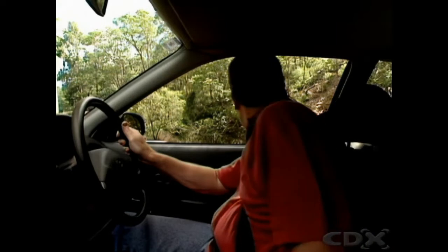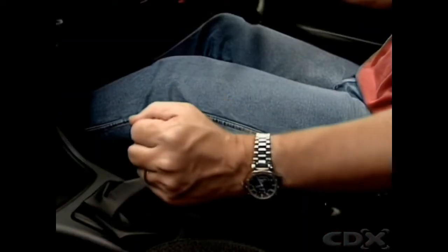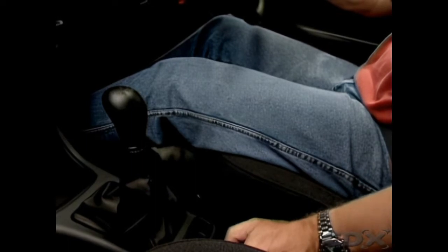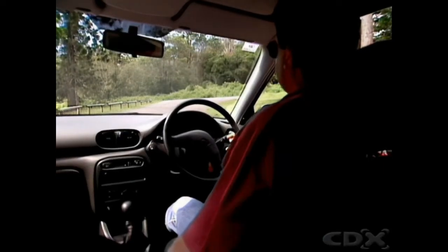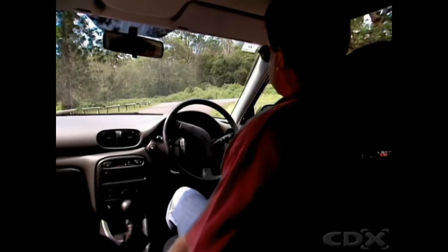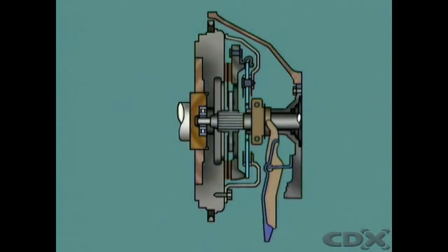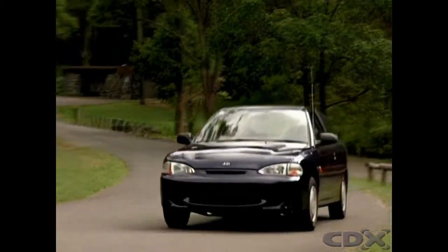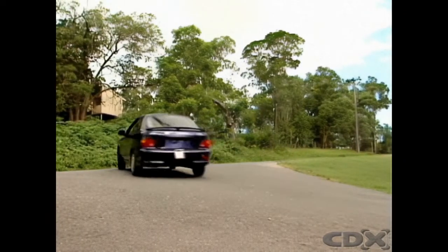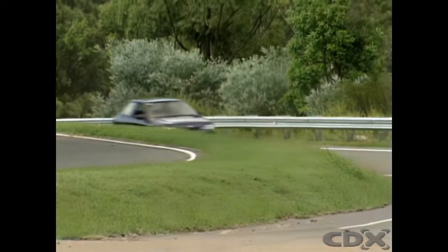When placing the transmission into gear, the transmission input shaft must be disconnected from the engine. When moving the vehicle from rest, slowly releasing the pedal gives a gradual engagement of the drive as the friction facings slip and allow torque to be applied progressively until both units are rigidly connected.